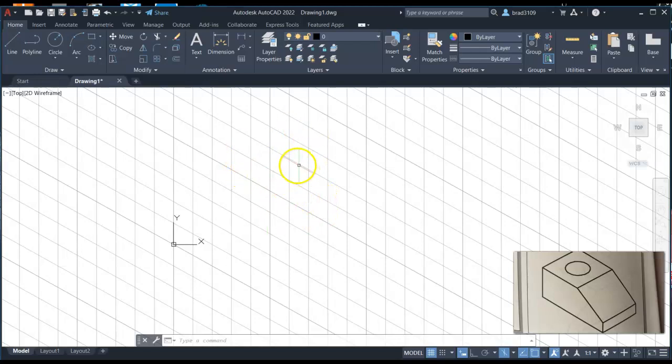As we look through the textbook, the first line that we're going to start to do is create some construction lines. So let's go ahead and activate our construction line layer, and we're going to go to the line tool. Notice at this point, I don't really have anything where it's picking up on the grid. So let's turn the snap mode on the grid, and we can start to pick this up. This might get in our way a little later, but for right now, we're going to use this to get started so we can place some things here.